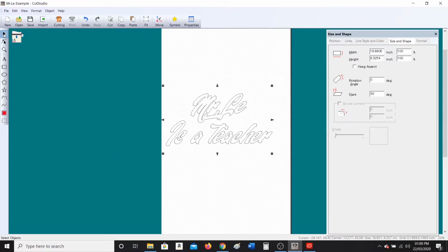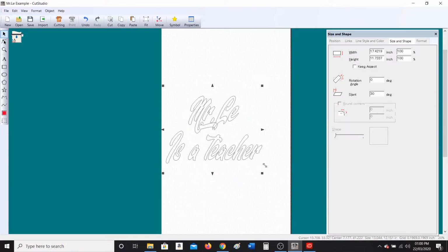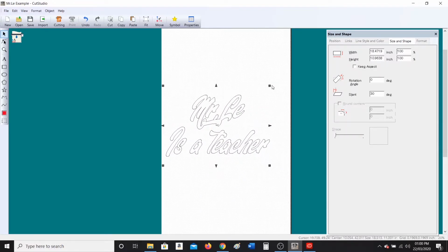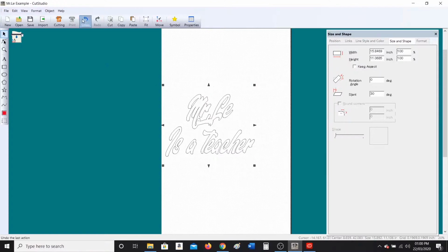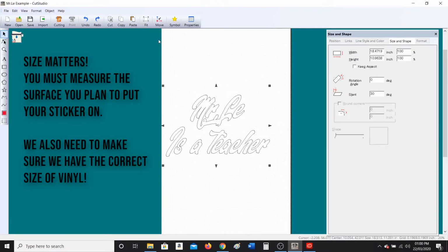Obviously, if you are on the select tool and you have your font selected and you move one of these corners around, it works and it skews your words. When we need to get more specific in terms of cutting on the vinyl cutter and the piece of vinyl that you cut off, we need to focus here on width and height where we type it in.